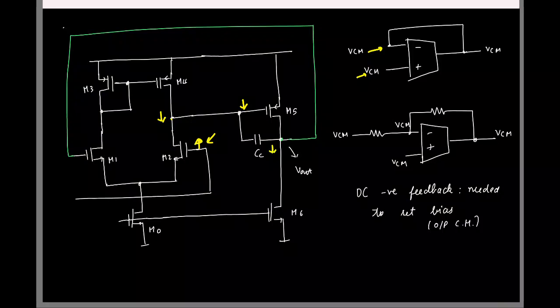And here I'll have the bias voltage set. So we also saw the range of the common mode that you can apply at the input, right? So what do you think will be a reasonable choice for this input common mode? We saw a range of voltages, but what do you think would be a reasonable choice generally? Right, because we are operating from 0 to VDD.